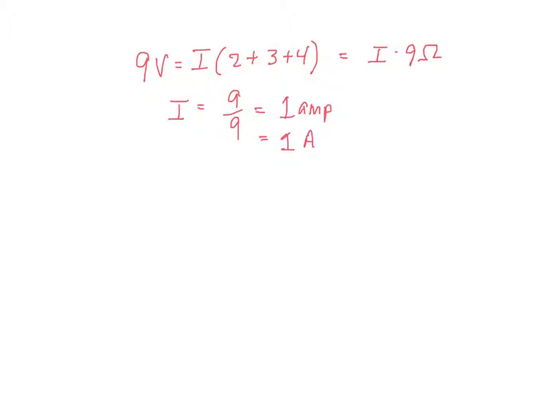And that allows me to size the wire. It allows me to design a circuit breaker of the right size to put into that circuit to trip if there's more than 1 amp going through the circuit and it's designed for 1 amp. The wire is designed for 1 amp. I might have a circuit breaker to trip with a little more than 1 amp.